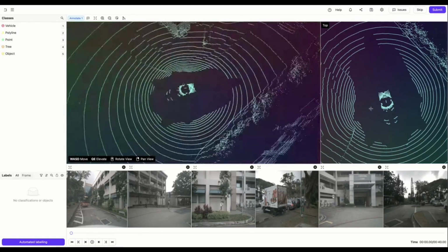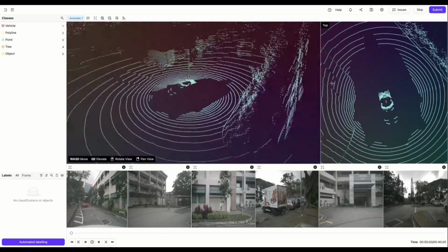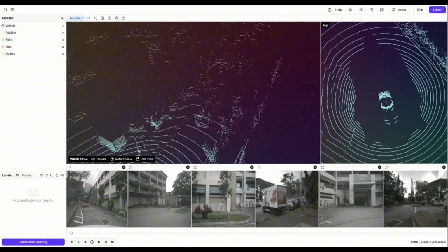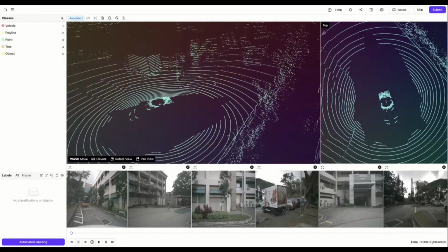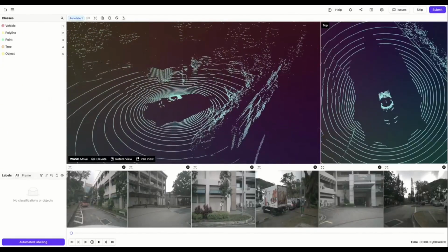And if I do that, then I can swivel around the 3D axis like this. Using the right mouse button, you can click and hold that down. This actually lets me move around like so. So I can move around and then I can swivel. And then you can also use the mouse wheel to zoom in and out of the point cloud like this.